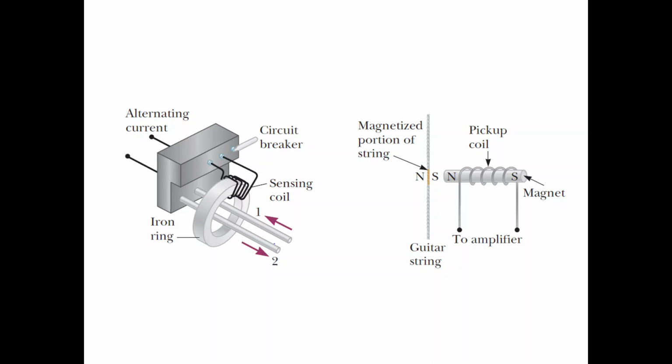That will create an excessive magnetic field and an induced electromotive force in this coil. Once this induced electromotive force is detected by the electric circuit of the differential circuit breaker, it will just open, switching off the electric circuit, and there will be no current supplied to the house. So that's an option for how you can protect human beings from being damaged by electrical current.